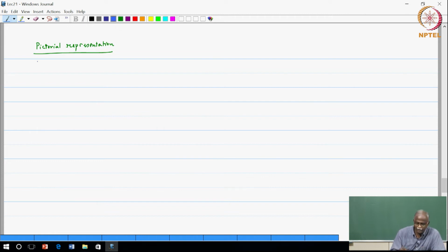This takes a little bit of time to draw, but it's worth the effort. Okay, I am going to have 2 filters, H0 and H1, which are approximately of same bandwidth. So, which means that somewhere around pi by 2 they should cross over, but there is no other constraint. If my input signal is Nyquist sampled, then I have information content all the way from 0 to pi.